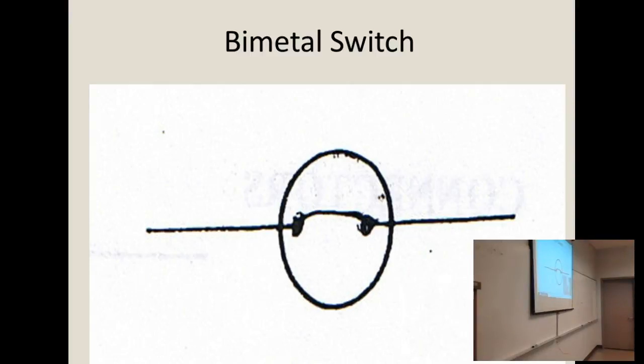So what is the switch stopping? Electricity. Yeah. Okay, so I've got electricity going to my gas valve. And let's say for some reason the blower motor, the fan, doesn't run. So it gets hotter and hotter, and there's no air coming out into the room, so the thermostat still wants heat. And instead of the furnace catching on fire, this thing will warp and cut the power to my gas valve, and be a safety.